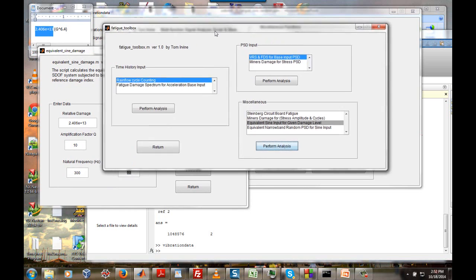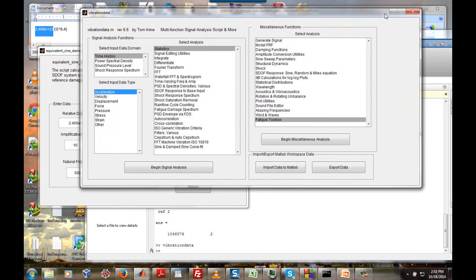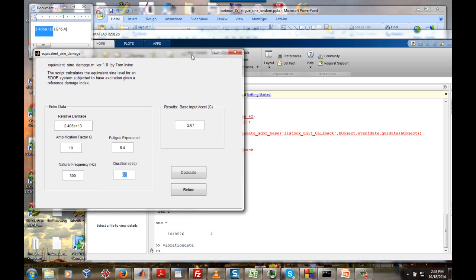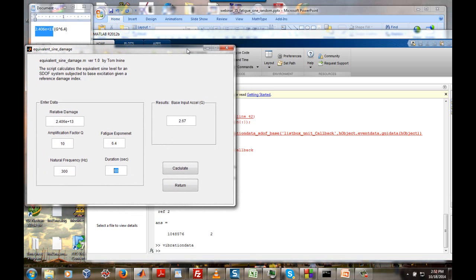Another thing, and I do need to be honest and upfront with you here, is that we do the best we can. We're engineers, we're not physicists. And I've been in meetings with some of my esteemed colleagues who say, and understandably so, that anytime we're doing our analyses, especially like a finite element analysis or whatever, these Q values or the equivalent damping, that's the biggest uncertainty factor. And to some extent I agree with them, because damping can only be measured. It cannot be predicted ahead of time.